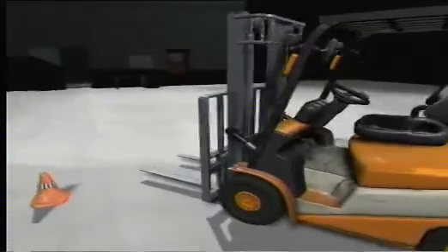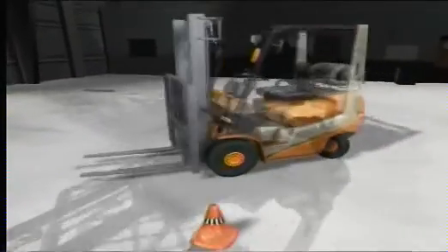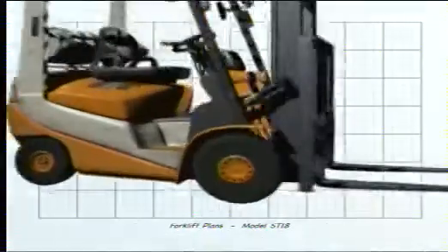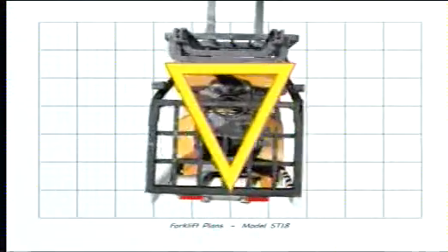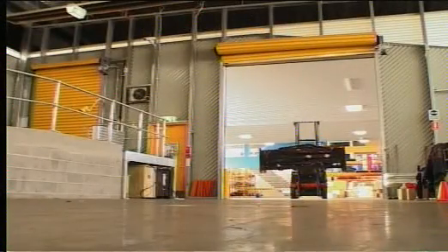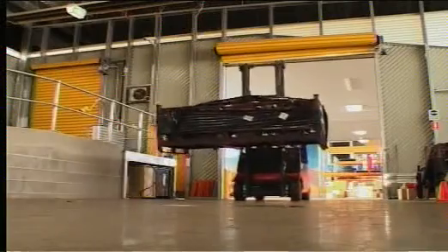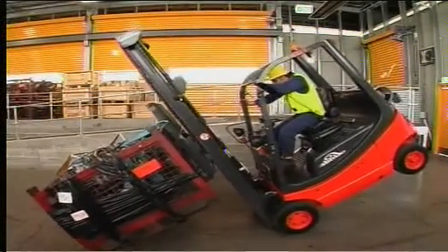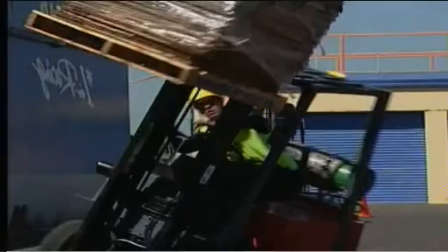Although most forklifts stand on four wheels, the hinged rear axle makes the forklift behave as if it was standing on only three wheels. This creates a stability triangle that is used to determine a safe center of gravity when operating a forklift. The corners of the stability triangle are formed by the center of each front wheel and the center of the rear axle. The center of gravity of a forklift must be kept within the stability triangle when the forklift is either static or moving, or it will tip over. A forklift's center of gravity can move outside the stability triangle in two directions: longitudinally, forwards and backwards, and laterally, sideways.